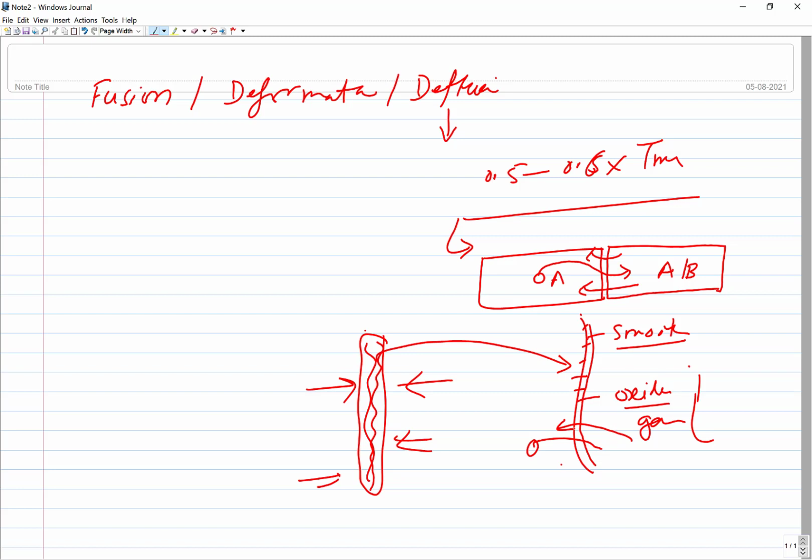So in order to deal with these issues, a lot of innovative approaches are used, so that diffusion can be accelerated, or not much smoothening of the surface is needed, because that is a very tedious task. So longer diffusion time and very good surface preparation are the two bad aspects related with diffusion bonding.